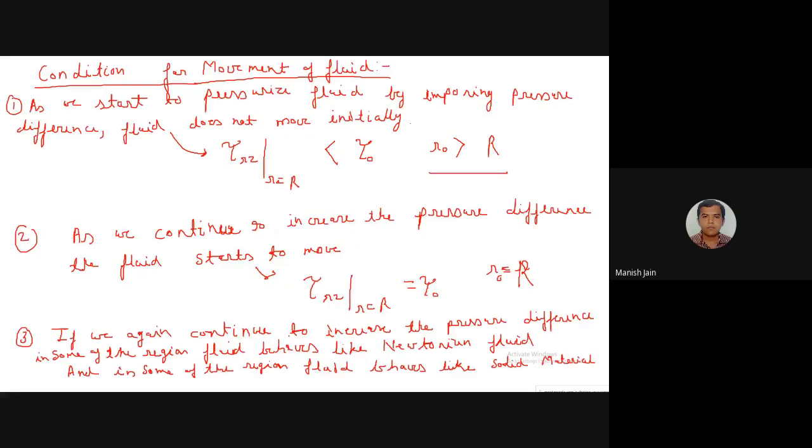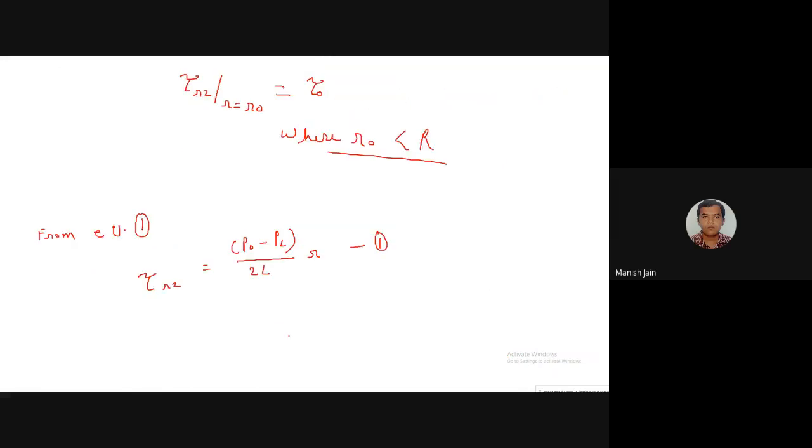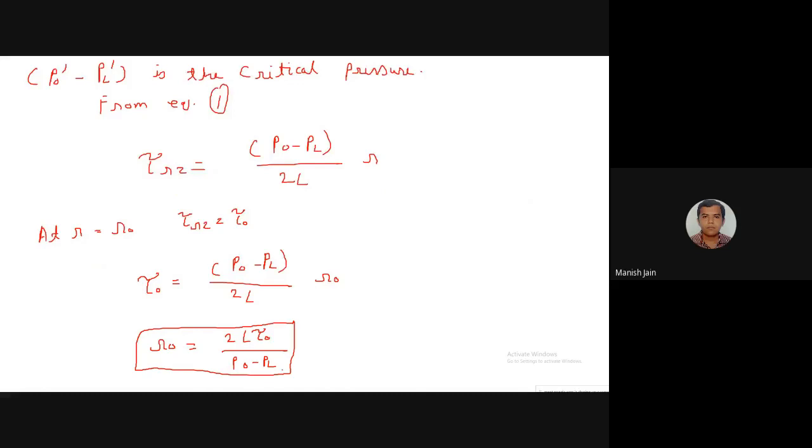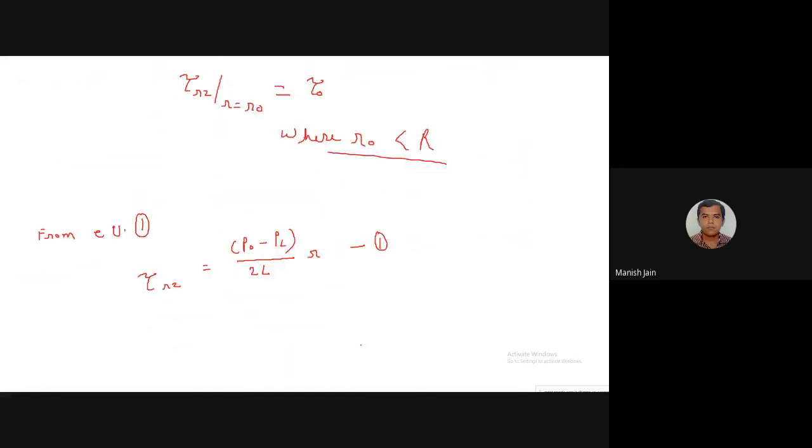Suppose I am giving you this type of material, a type of gel, say silica gel or any gel. For that type of material you should know the value, like the value of viscosity is known for fluids, for example the viscosity of water. These are known quantities, and this is a physical property of the material. Similarly, tau naught is also a physical property of the material, which should be known, but R naught depends upon the structure and the geometry of the flowing channel. So the value of R naught you have to calculate during the derivation. Okay, so here we calculated the value of R naught, which was unknown. This is equation number 6, I think.